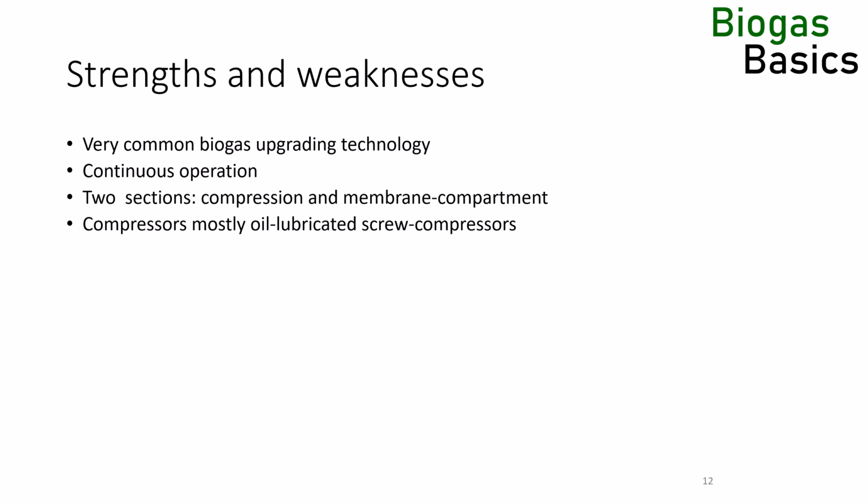Now let's invert the problem. How can we break a membrane-based biogas upgrader? Membrane upgraders are sensitive to 6 types of contamination: water, ammonia, VOC, H2S, siloxanes, and carbon dust. When an upgrader shows a deteriorating performance, it is almost always because of one of the 6 reasons.